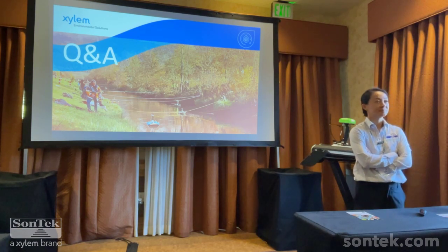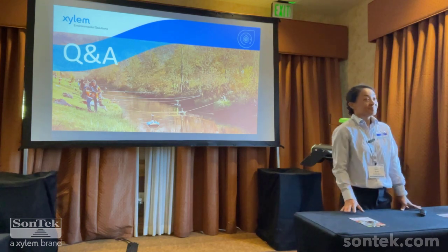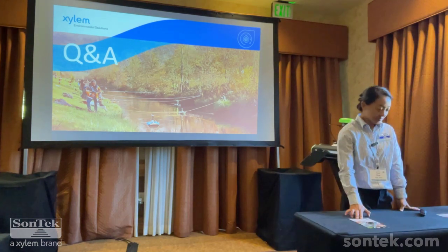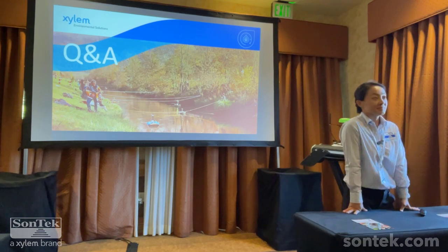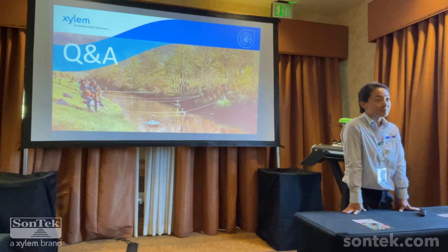I work with a customer in Thousand Oaks who's new to this, and they're a little overwhelmed about FlowTracker measurements, ADCP measurements. What's powerful about the RS5 is you can use it for most use cases. They have a bridge there, and it's actually a really easy way for someone with very little hydrology experience to cover most use cases to build out their rating curves. It's pretty exciting to have something so easy to use that you can give it to a wastewater operator who can go out and take measurements over the course of the year.